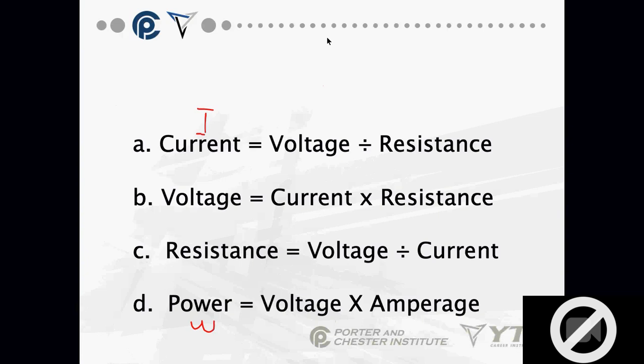Okay, now you can actually pull this back to what we consider the pie chart, and I'll show it to you in a minute. If you think about it in a pie, you can actually draw a circle, take your slices of a pie, and E, which is voltage, equals I times R. So if you're ever asked an Ohm's law question on an exam and you have scrap paper, just immediately write down the pie formula here. We can do the same thing with watts.